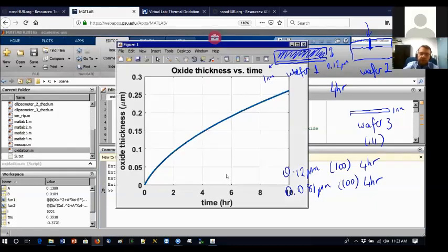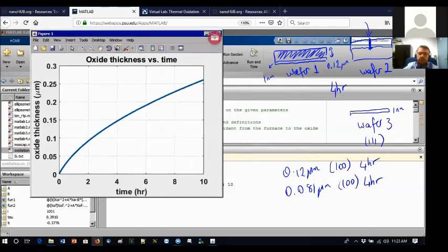And at the end of the 4th hour, let's see. What do we expect? We expect a thicker film. Again, doing the same, going to the data cursor, putting it on the plot. I somehow magically put it right at the bullseye, so it gave me the result. How much did I grow? 0.1466 micrometers.